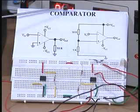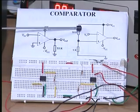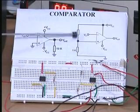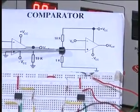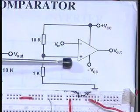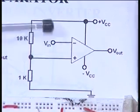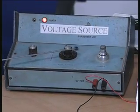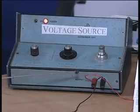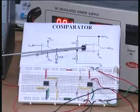Here this is the comparator. I have put two circuits here. I want you to first concentrate on the circuit to the right. You have a potential divider, a 10K and a 1K, and the midpoint of that is connected to the plus input. To the minus, the inverting input, I am going to give an input from a millivolt source. This is a familiar millivolt source which we have used in a number of our experiments, and I can vary the output voltage using these knobs. That is connected to the circuit at the input corresponding to pin number 2, which is the inverting input.